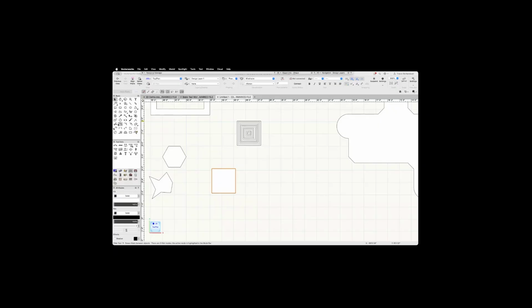So underneath the scissors in the basic tool set, there is the Move by Points tool. I can select that. Again, it's got a variety of modes. We're going to mainly work in move and duplicate mode. And over here you can set the number of duplicates that you want to have. So with this rectangle selected and my Move by Points tool activated, I'm going to click on the center of it, and as I move my cursor to the right, you can see that it makes more and more of those squares being evenly spaced along a specific distance, and that there are going to be 5 of them.